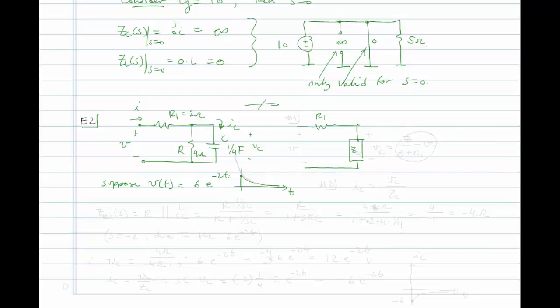where I have a resistance R1, and then I lump these two, the R and the C, together, call it Z, and then I'm going to find the voltage across here, which I should call VC, as being equal to just Z over Z plus R1 times V, which is over here. Right? I'm going to use the voltage divider. So this is going to be step 1. Right? Then step 2 is going to be,